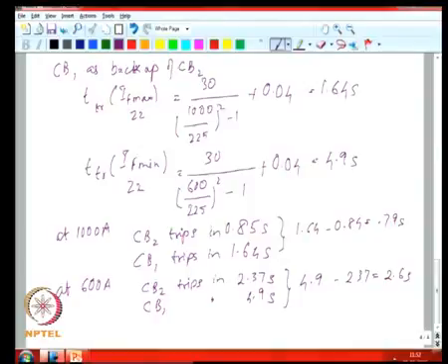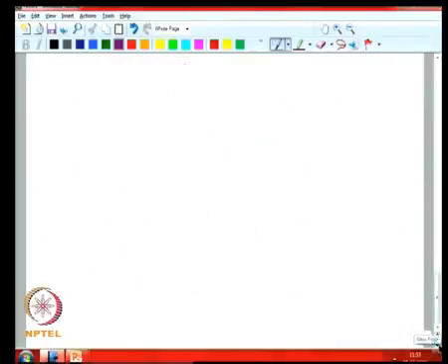So you may not have nuisance trip problems of breaker 1 for some reason operating before breaker 2 for a fault in zone 2. Then you can calculate the I square t level corresponding to a fault in zone 2 and breaker 2 failing to operate.